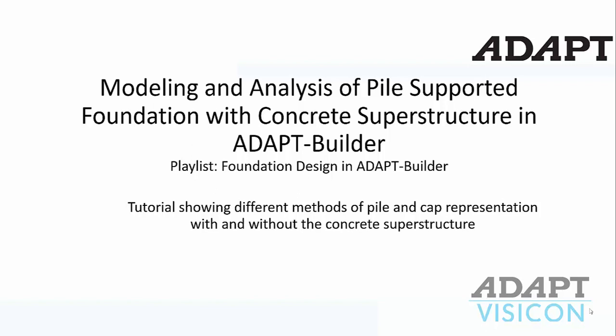In this video tutorial, we're going to explore a method for modeling and analyzing a pile-supported foundation with a concrete superstructure in Adapt Builder. And we're going to attempt to model piles using column elements with lateral springs at different increments along the depth of the pile, along with the full multi-story structure in Builder.